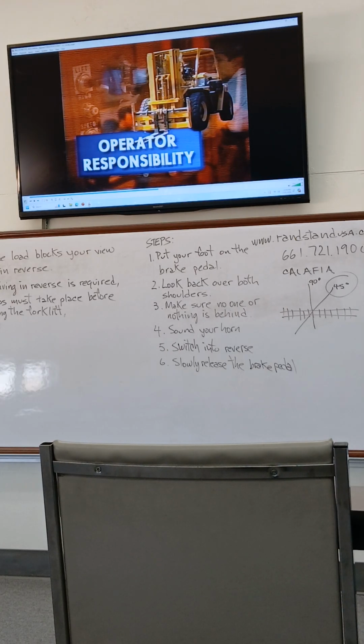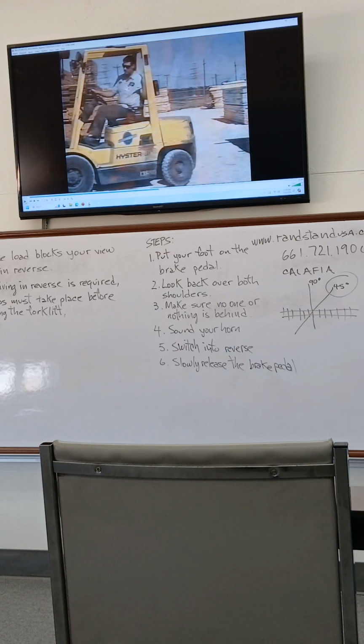Do you have any questions? Yes, sir. Operator responsibility. First of all, how many types of forklifts? Because he has seven types of forklifts. Seven classes. And so I just learned today for 4 and 5, right? Mm-hmm. Yeah, we train for 4 and 5 today. Okay, and second of all, over there they have a number plate. So how do I check the weight? So the plate. Yeah, all the forklifts are going to have the plate, so you can see the load capacity and all that information. So yeah, it has to be there on the forklift.